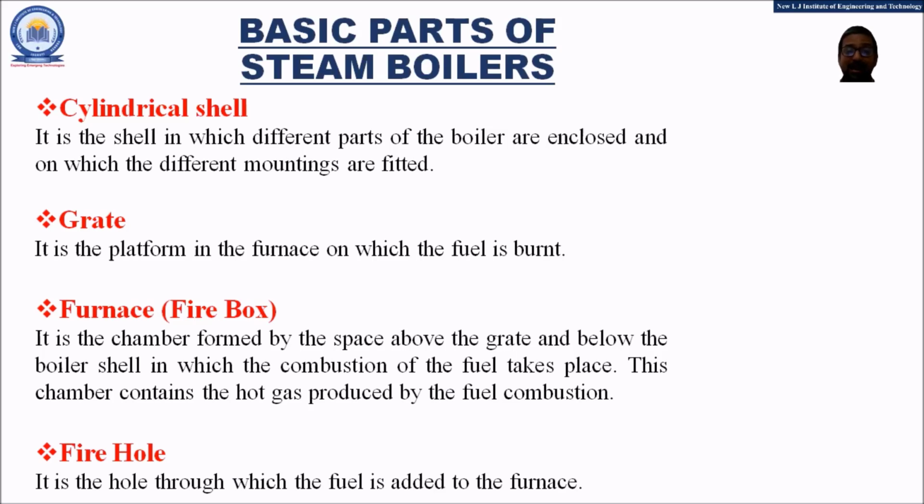So let me combine these three concepts. Through the fire hole, the fuel will be entering the furnace. The fuel will be collected on the platform, that is the grate. And on this grate, the combustion of the fuel will be started. The fuel will be burnt, and thus the hot gases will be generated by the fuel combustion.